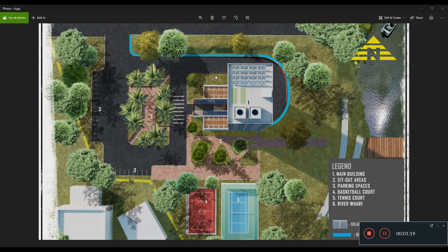Now, looking at the case studies I've done, I've tried as much as possible to put some of the strengths I was able to find in those analyses in my home building. One of them is the solar panels which I have on my rooftop. Now, the general guideline, because there's a guide for placing solar panels on the roof: for tropical climates, Nigeria to be specific, I discovered that to capture much of the daylight, it's advisable to face the solar panels to the south elevation. This will help in capturing as much daylight as possible and push the solar panels to their maximum efficiency.